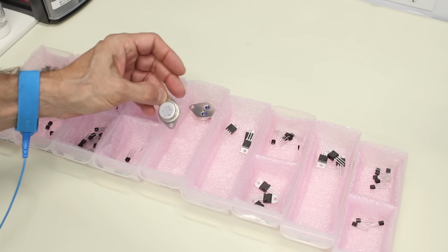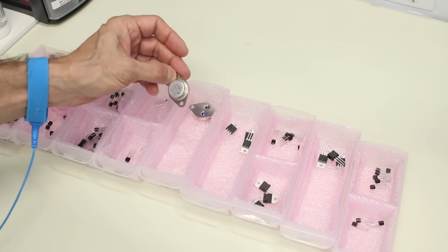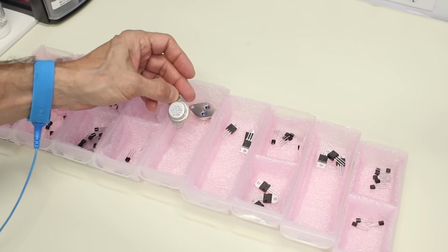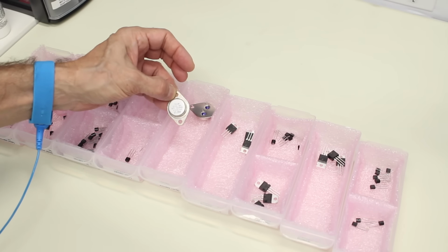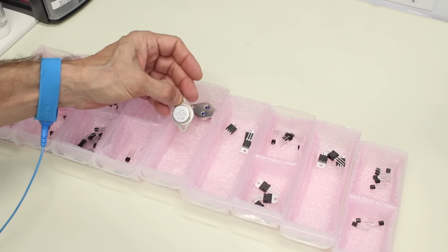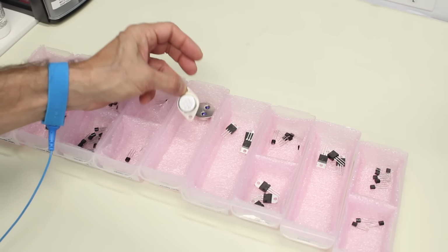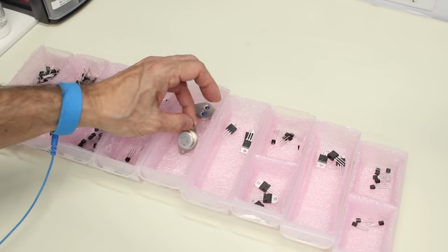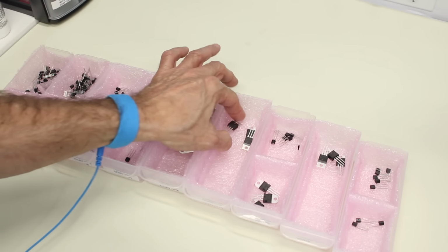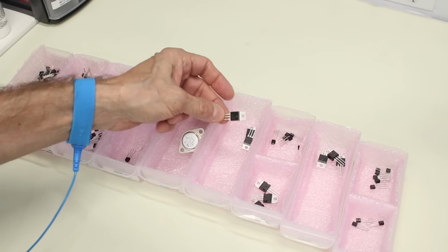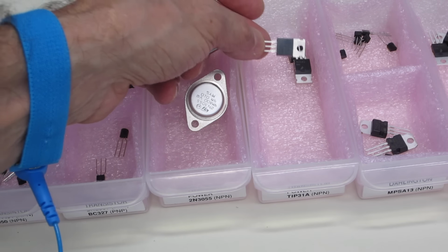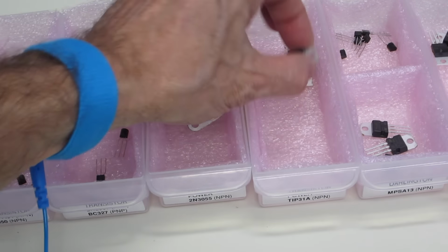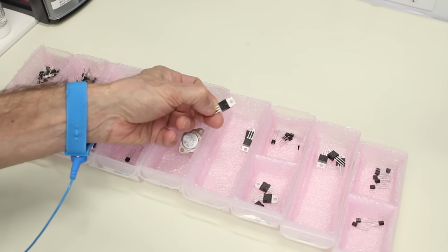Usually we use things like mica insulators to connect them onto heat sinks while insulating them electrically. The mica insulator will allow the heat to transfer. There's other materials other than mica that they use nowadays. I'm kind of old school as far as that goes. This is a very common package for a power transistor. It's called a TO220. In fact, the ones that we're going to use today, which are the ones over here, are in a TO220 package.